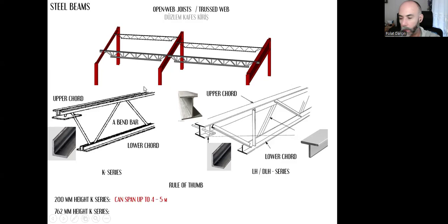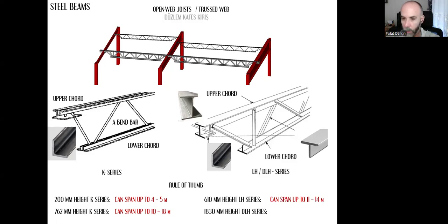A 762 millimeter height K series can span up to 18 meters. This 610 millimeter height LH series can span up to 11 to 14 meters.